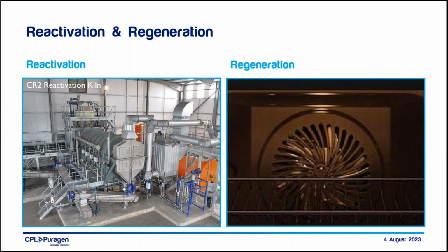Some of you may have heard about reactivation and regeneration, and there seems to be quite a bit of confusion about the difference. Reactivation is a complex, high-temperature process involving several steps. The first step is drying at 150 Celsius to remove water. The next is thermal evaporation at up to 250 Celsius to physically desorb volatile compounds.